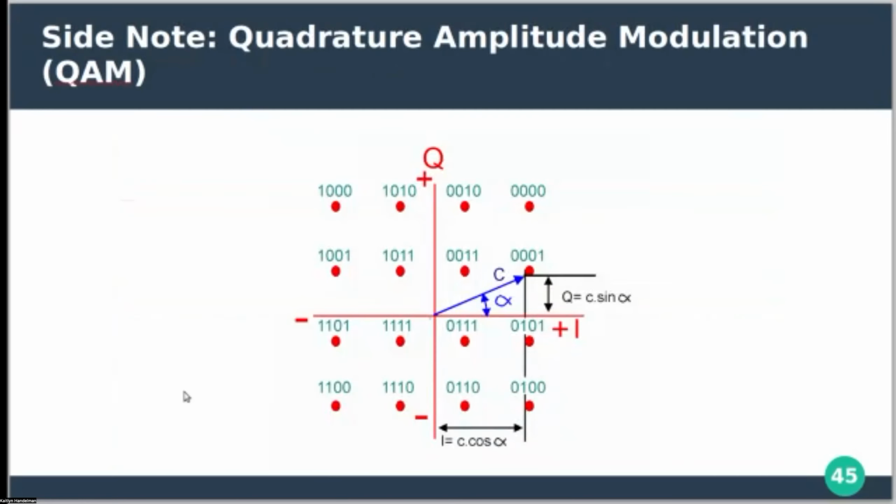And like I said, if you get a good signal, you can code way more data. And this is how we're getting really, really fast Wi-Fi. So like I said, the quadrant that the in-phase and quadrature signals go into is based on phase, but where it lands in the quadrant, like if it's close to the center point or far away, has to do with the amplitude. So we can encode amplitude and phase into something called quadrature amplitude modulation.